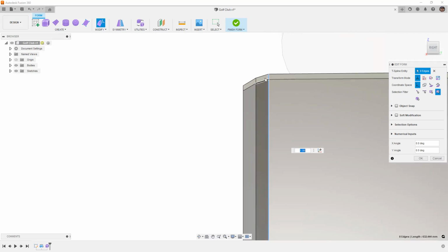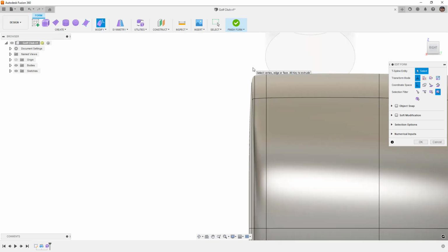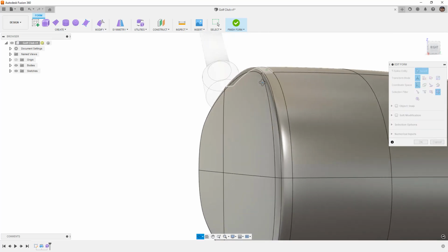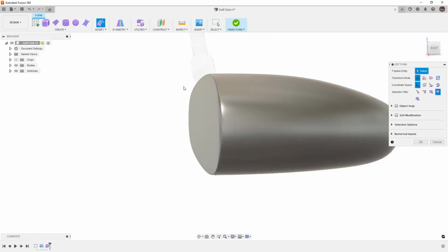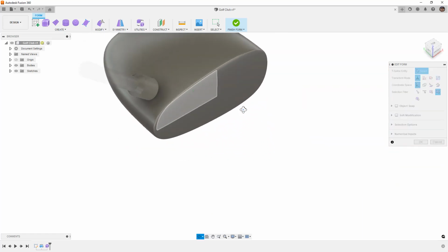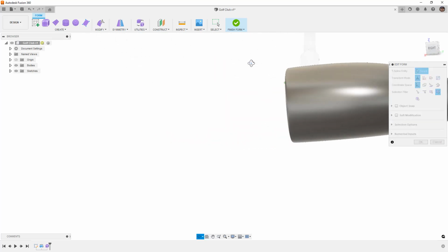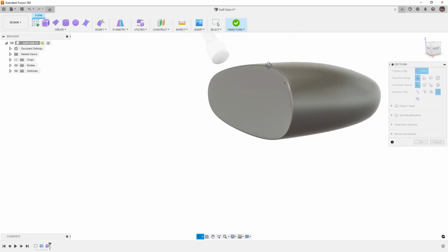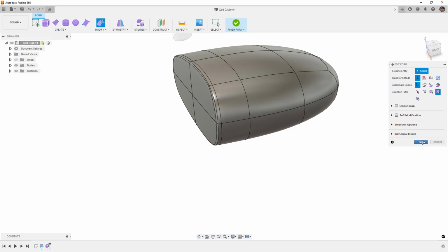And what we're looking for is, we don't want these two edges to be collinear. We don't want them to be straight. We want a little bit of angle between them. So if I look at this in smooth display, we can see that now we're controlling that edge a bit better. I'm going to use Control and 4 on my keyboard to hide the edges to show that this is not a perfect solution. We're not done with this yet, but it does allow us to sort of control those edges. Before we get on to controlling the edges flowing back, I do want to talk about